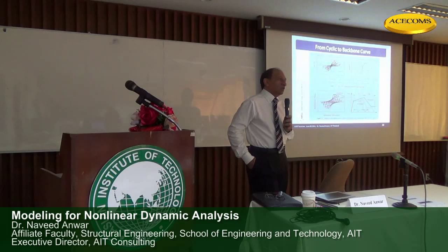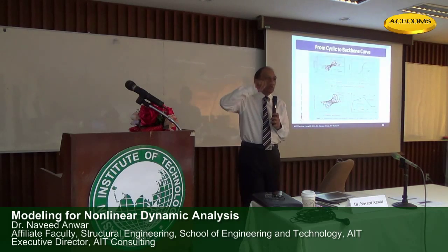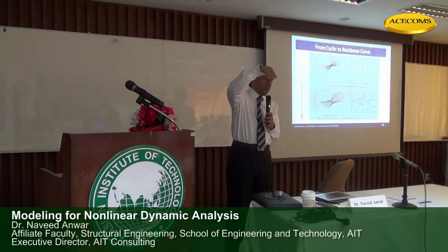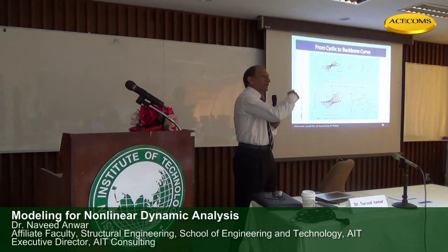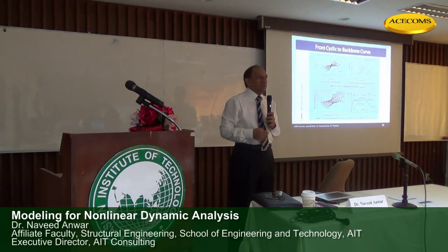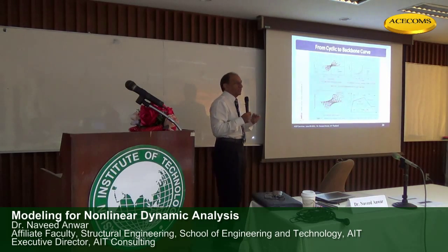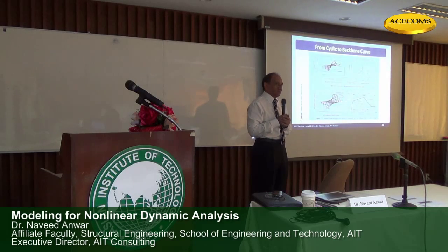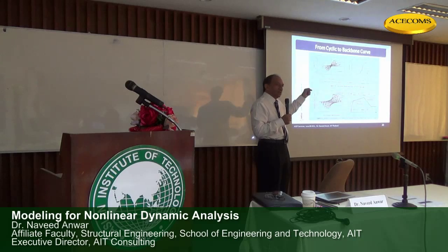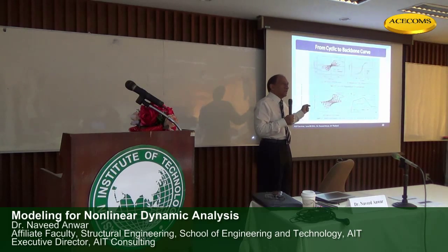In pushover analysis, because it is not cyclic, we try to modify the backbone curve of the material to match with the equivalent cyclic response, and that is one of the key shortcomings or simplifications that we need to do in pushover analysis. In time history analysis, we can use the actual curve, but that is also limited.